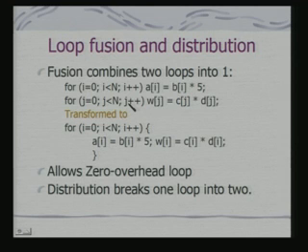But please keep in mind that although I have given these examples one after another and it became obvious that we can combine these two loops into one, this is not always obvious in the code. By looking at your control data flow graph, you can find out whether there are dependencies between such loops. If there are no such dependencies, you can decide to combine the loops and get what is called a zero overhead loop for some of the cases.